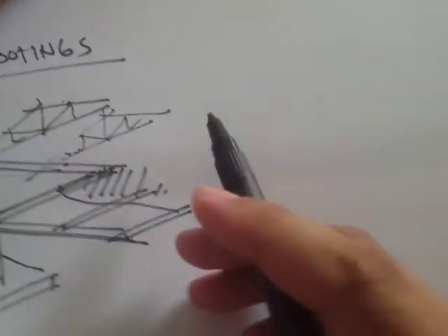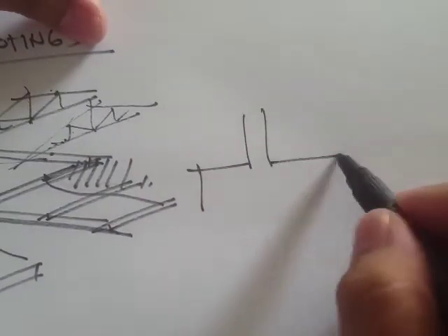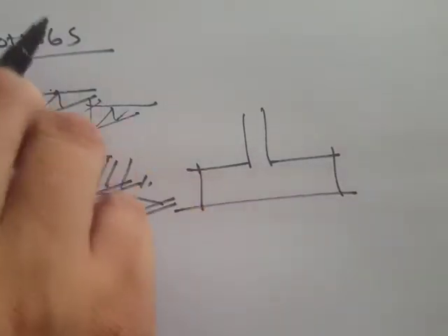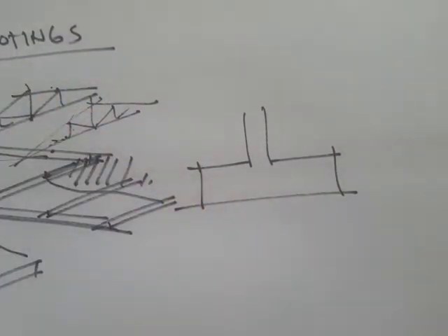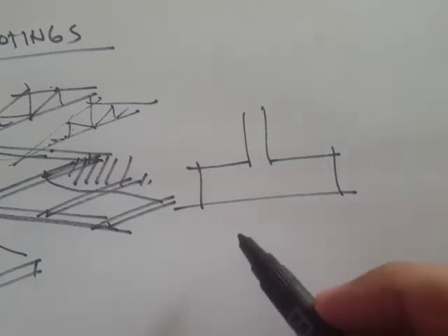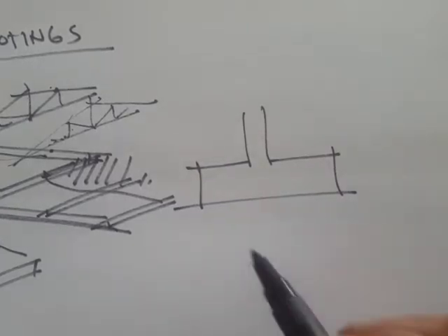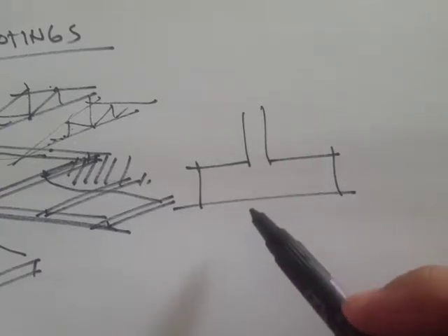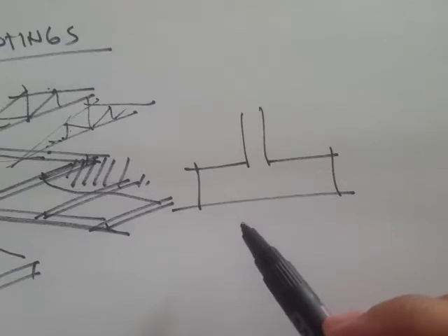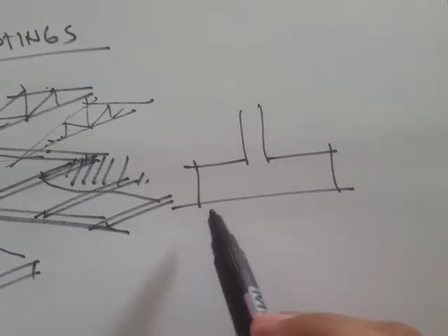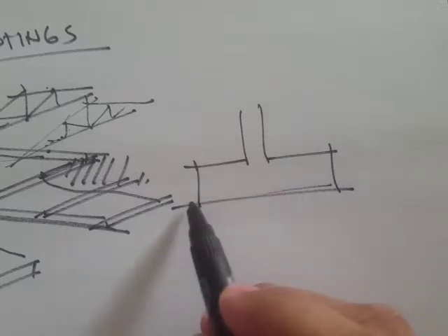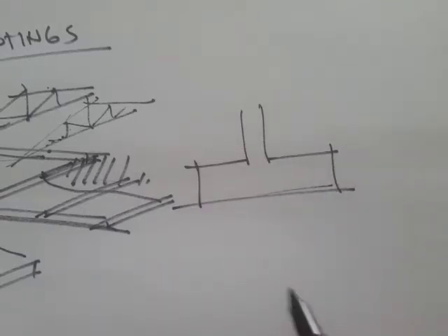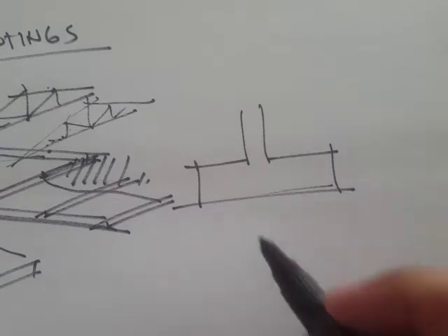Since footings are common to have a wider area, it's simply because the soil has lesser strength, or capacity, as compared to steel or concrete materials. So by spreading the area, by spreading the forces, the soil will be able to support the loads.